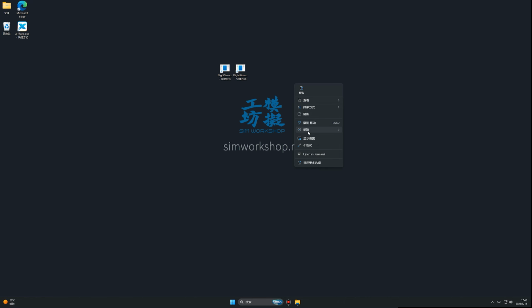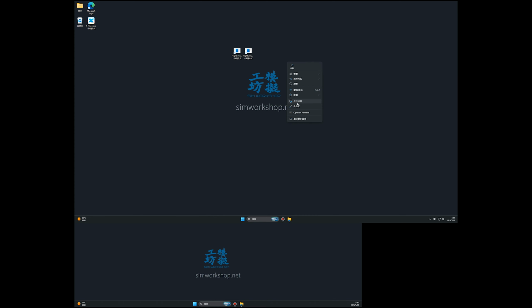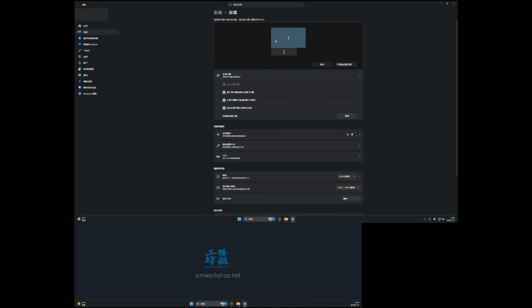After connecting the USB Type-C power cable and HDMI cable, open your display settings. The instrument display should now appear as a connected monitor. Select the display and verify that the resolution is set to 1920 by 550.